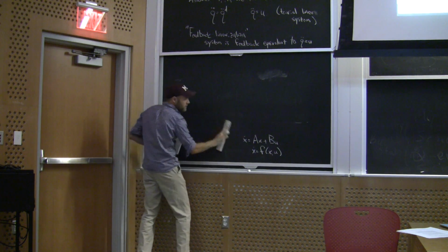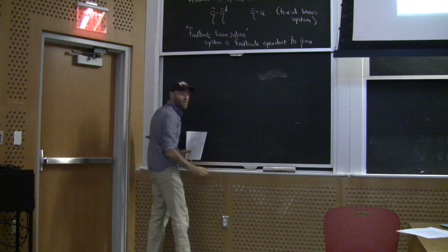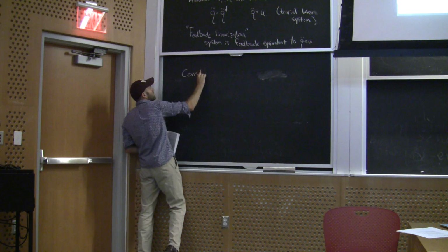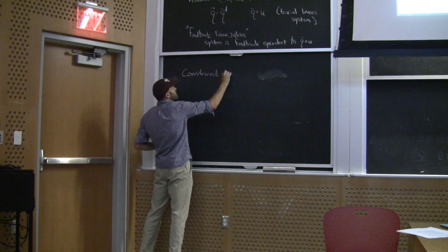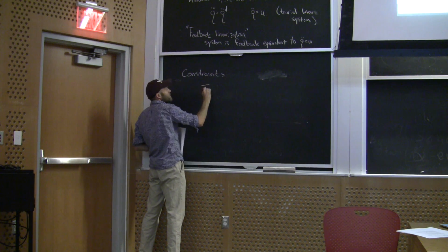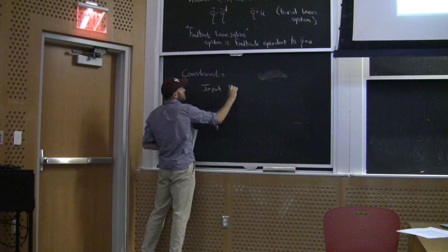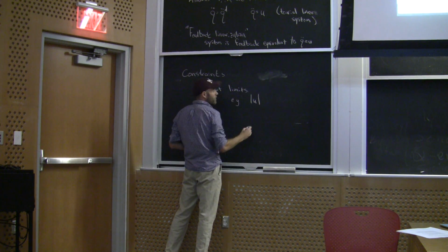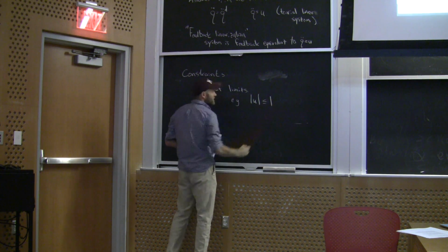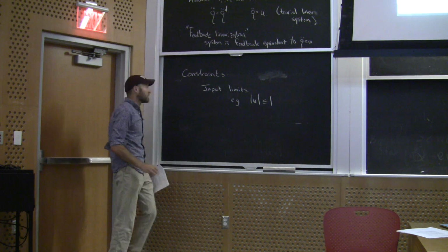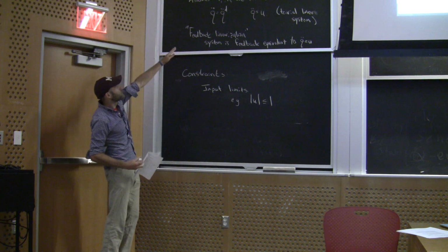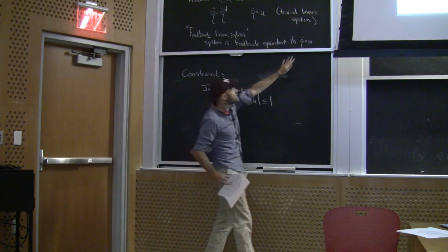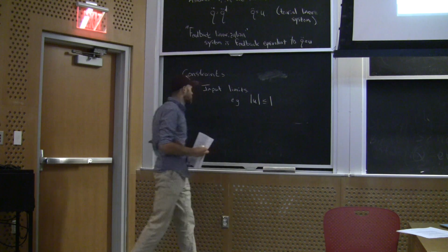Right, so if you're a little robot and you've got little motors, for instance, maybe you have input limits. Like my torques have to be less than 1 or something like that. That can also break this trick. Even if F2 inverse exists, it might be that I can't apply enough torque to turn the system into that linear system.